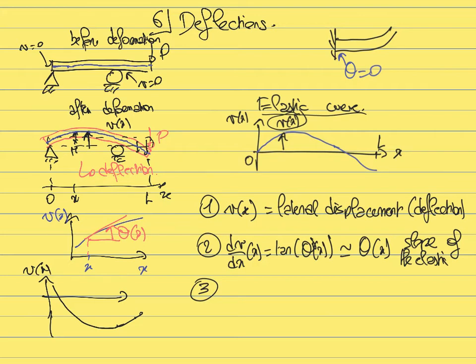And so one way to do this is, for example, if you want to know the curvature at a given position x, you look at this position, the curvature of the beam, and based on this, you can assume that the beam is roughly equivalent to a circle, and then you can define the radius of this circle.